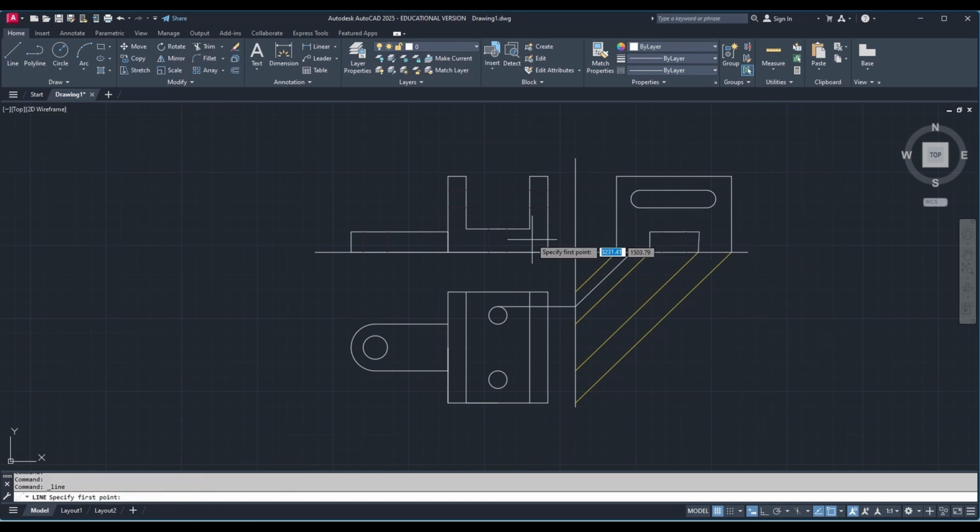above parts. Now I need to project these lines, and this is also basically hidden. So that's why I have not drawn it previously. So I need to make this line match property option and make it hidden. Now I will draw this one here, and then I have to make it hidden again.